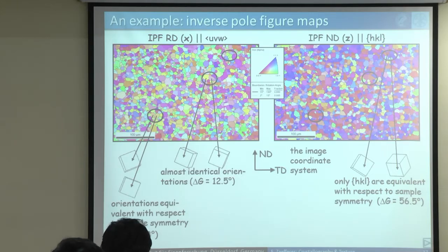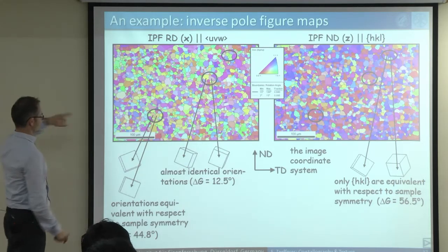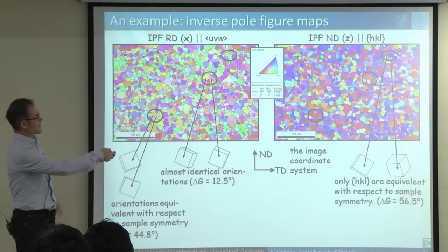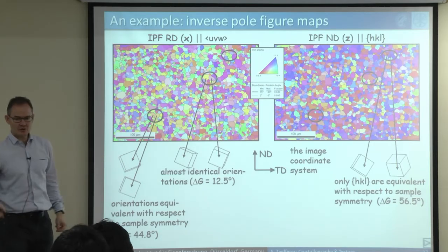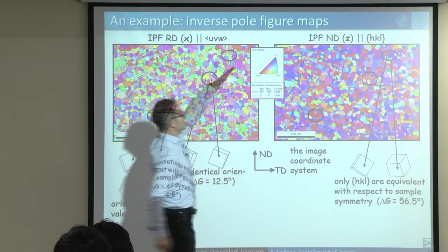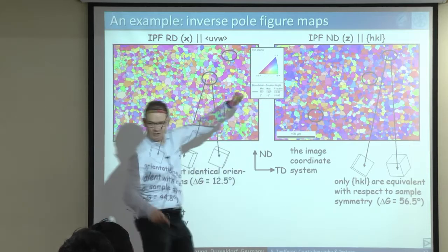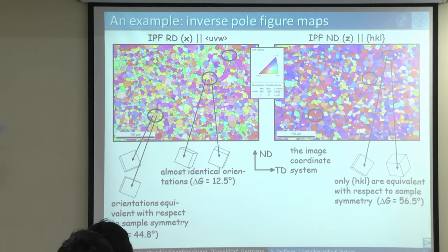Now, one of the serious problems is really, okay, if I have the same color but I do not have the same orientation, what is that problem? This leads me to just a short side remark. You don't have to digest that fully, but let me just make you aware of it. The problem is that when we create this color triangle, we do not consider that there is actually a mirror plane in here, which is not existing in the correct data set.